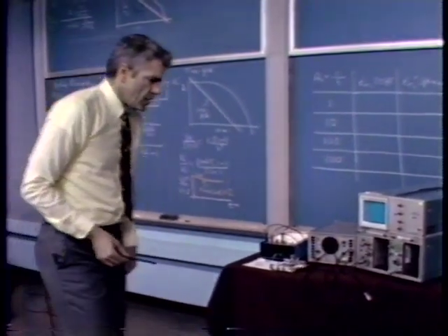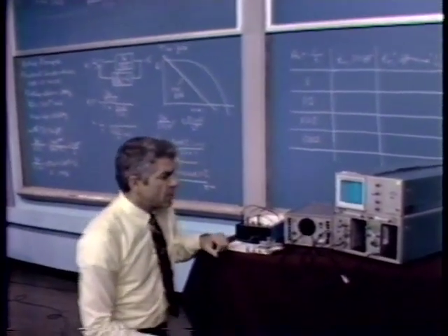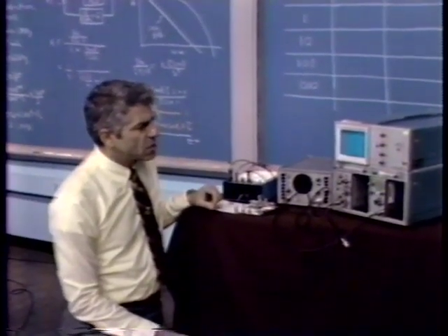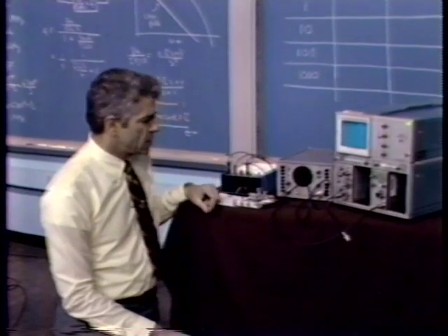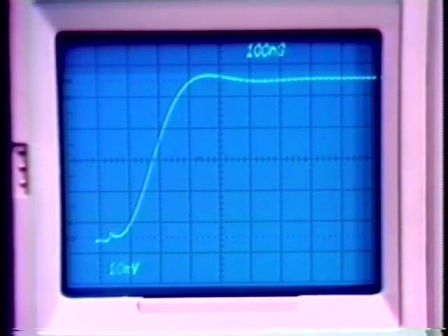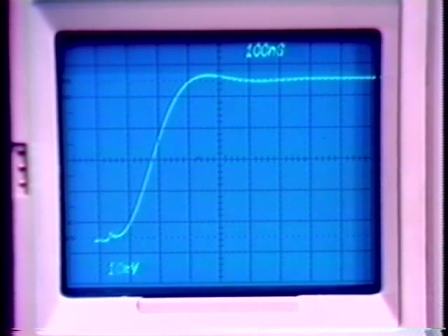With this particular amplifier, we found that we get very nice stable responses with just a small amount of overshoot, as presently shown on the oscilloscope, in unity feedback configurations when we use a 20 picofarad capacitor. Also, if we look at the transconductance of this amplifier, we find it's a little bit higher than the nominal value.